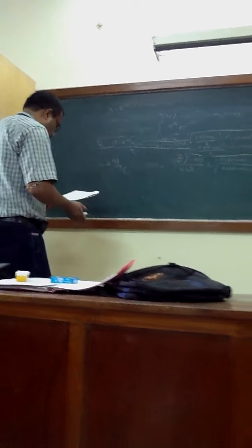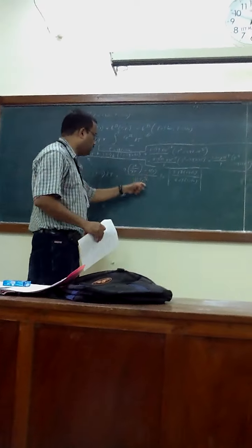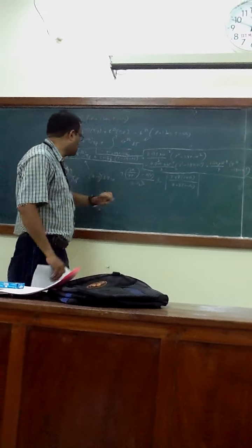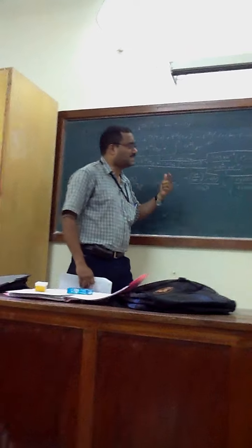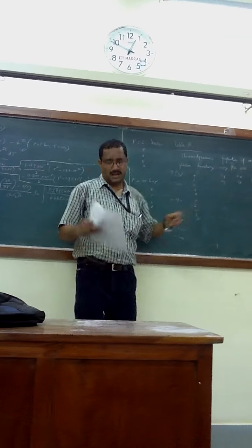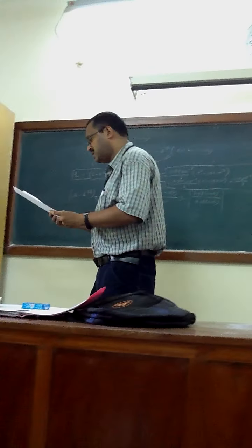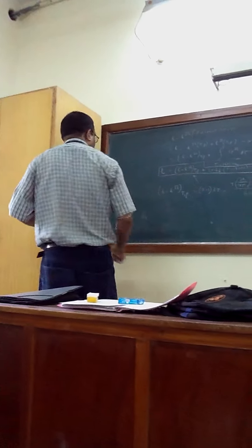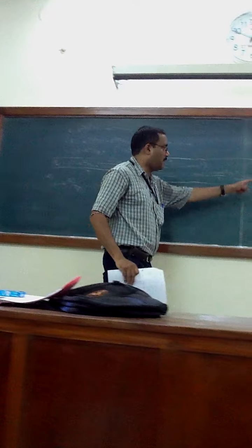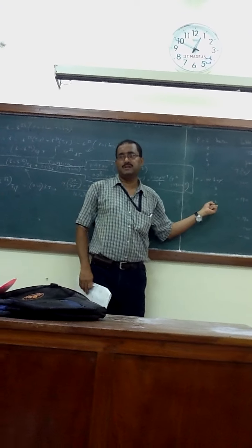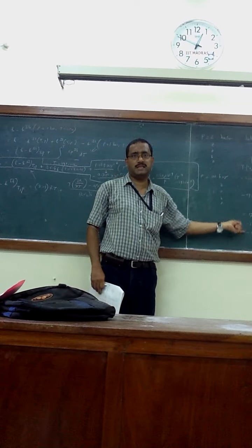We can do the calculation: dA/dT, A, B, everything is known, and you can get the set of H values. Similarly, one can calculate S minus S^ig. So this is done, your H part is solved. So you have Z, P, H in table A. Z is known, B is known, H is known.